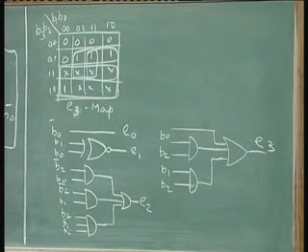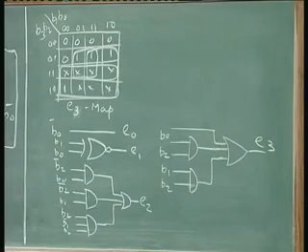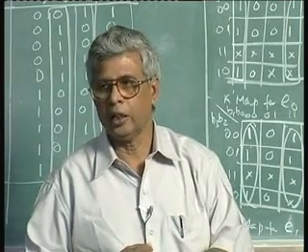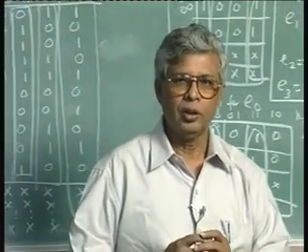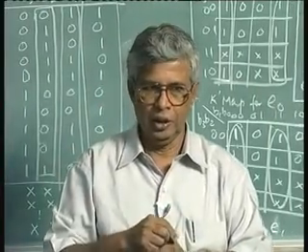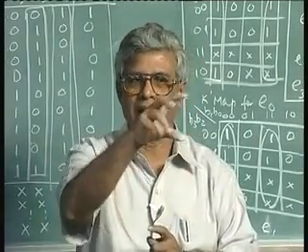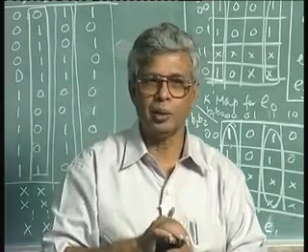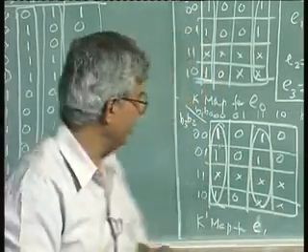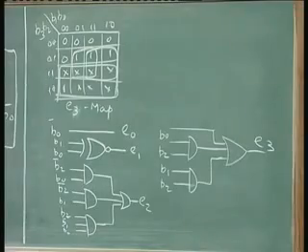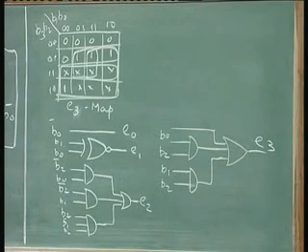That is, the binary code I will give you, the gray code I will give you, the truth table I will give you. From the truth table you get the values for the 4 bits of the gray code using the Boolean reduction technique using K-maps. Then draw the logic. So I will give you the table and the result. You have to draw the logic and verify my results are correct. Okay? If the results are wrong, that means you have done something wrong, because I am going to give you correct results. Okay? So let us talk about the gray code converter. Now this time I will do binary to gray code, not BCD to excess-3.